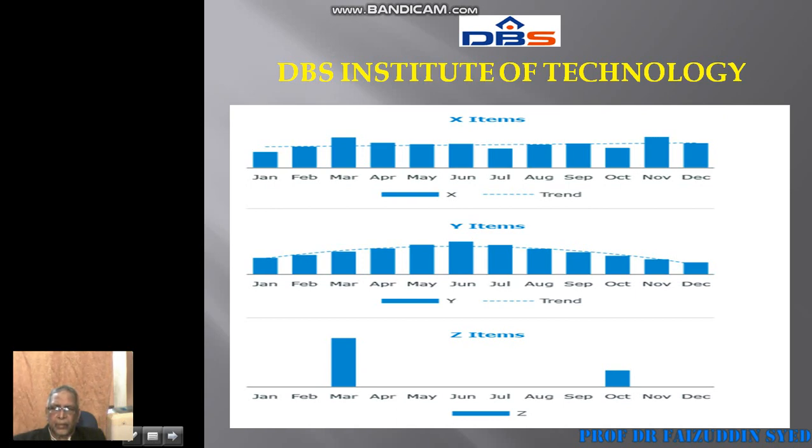So you have to know which part of this press is more essential and whether these parts are easily available in the market or not. Some of the items are not available in the market. Suppose if you order them, it will take 2 to 3 months. It means the press cannot run for 2 to 3 months. So such types of items should be kept ready in stock.